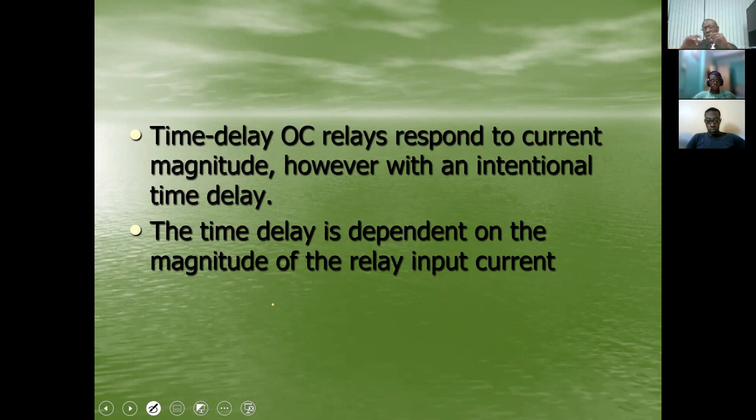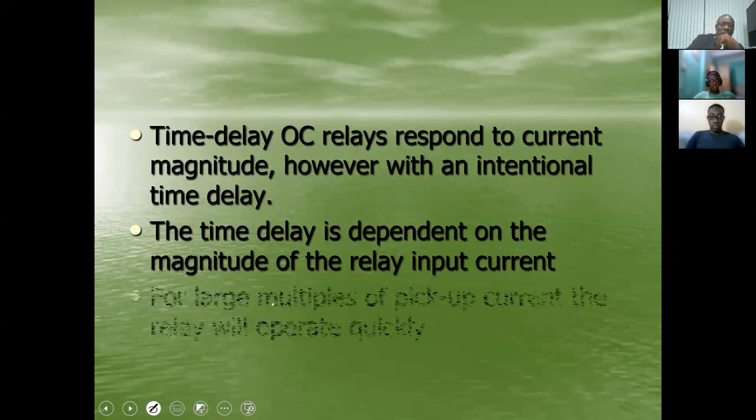All right. The one with the specific time attached, it really doesn't matter the magnitude above. It's going to operate in that particular space of time. Do you understand the distinction between the three? So you have an instantaneous, you have one that has an inverse relationship, and then you have one that is given a specified time to operate.